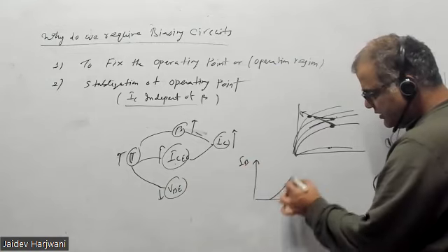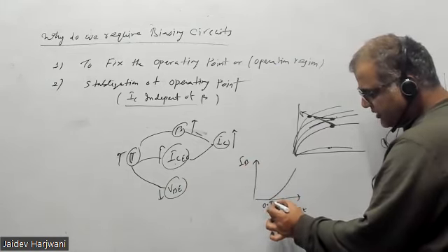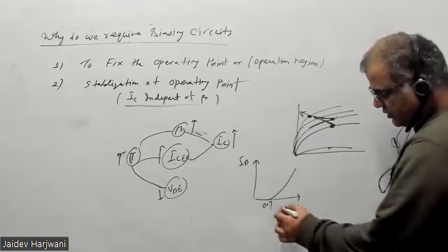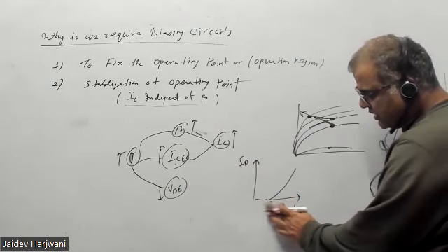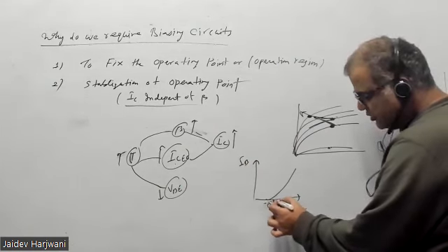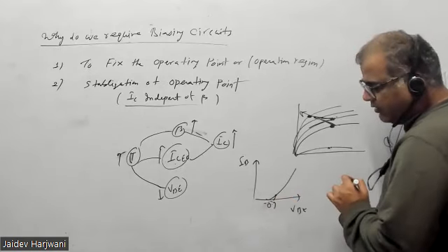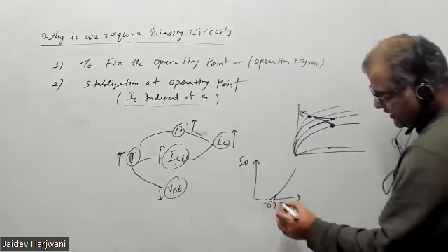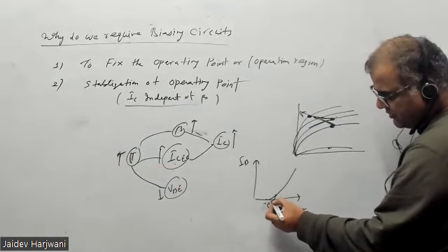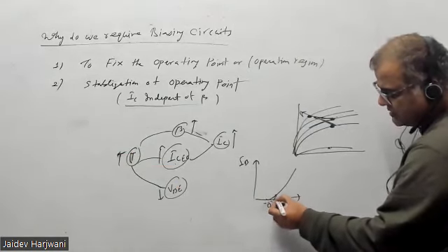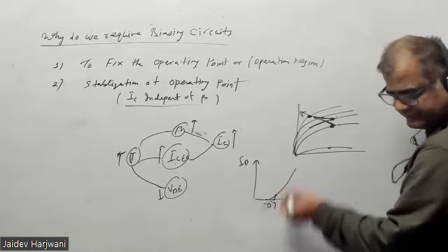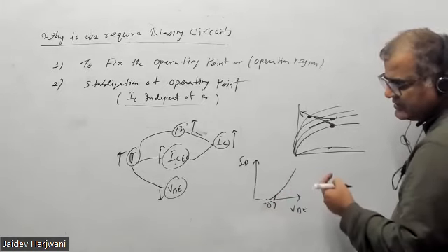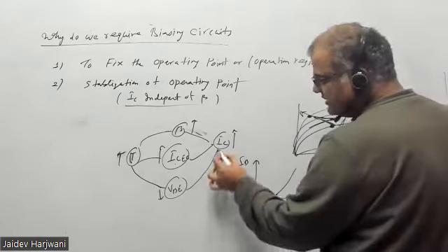Suppose the requirement is 0.6, you applied 0.7, so you are getting this current. Now because of the increase of temperature, you require less voltage, 0.6. So this 0.7 will give you high current, IB will increase, so automatically that will also increase your IC.